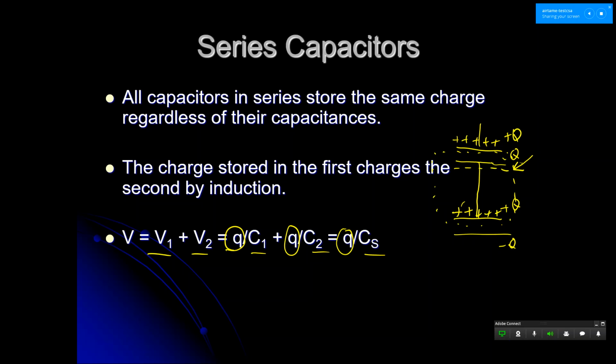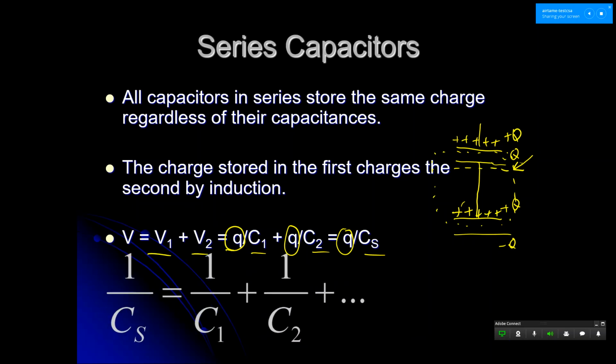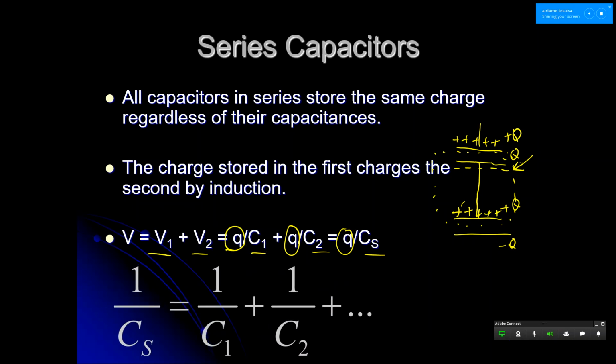And how we add the capacitance up in this case is by doing the opposite of what we did with resistances, right? So in resistors, when they're in parallel, you would do this formula, but now you use this formula when it's in series. You guys see how it's backwards from when you're talking about resistors? See what I did there?